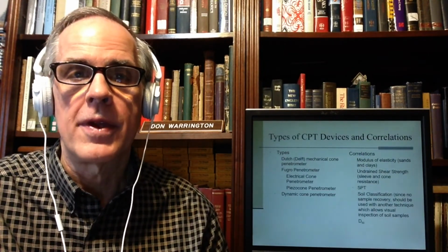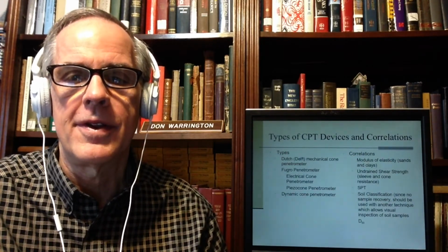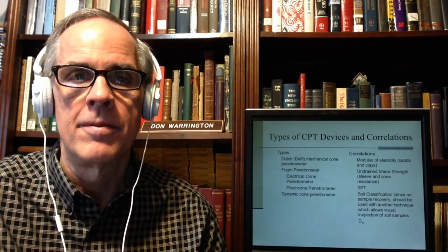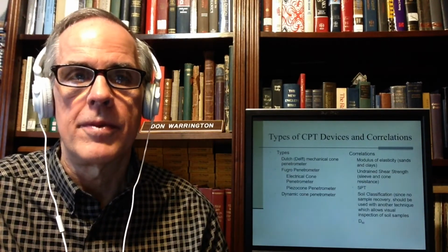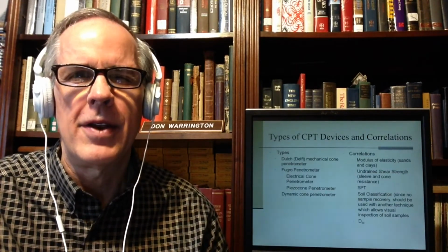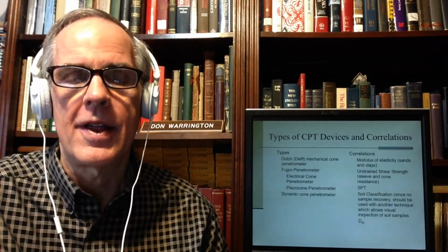One thing that I don't discuss in the lecture, our labs deal with it, is the dynamic cone penetrometer. This is kind of a combination of taking a cone and beating on it, rather like you do with the SPT.